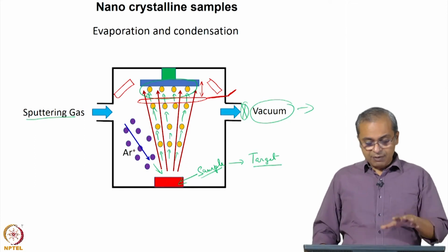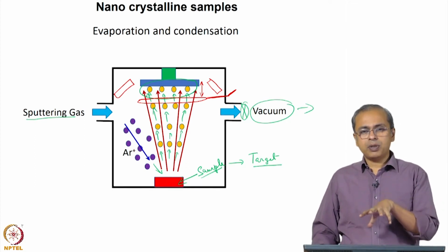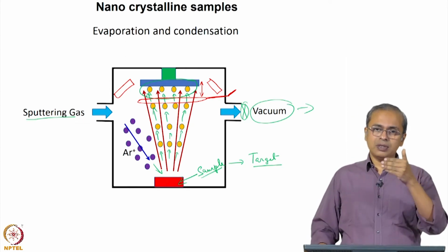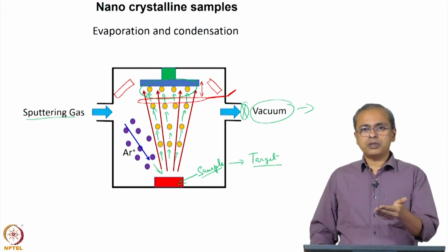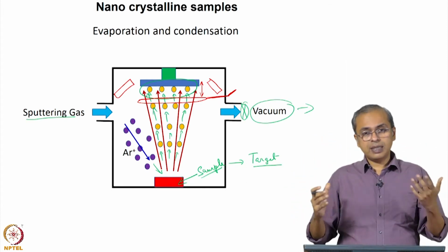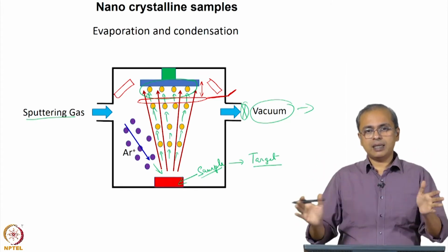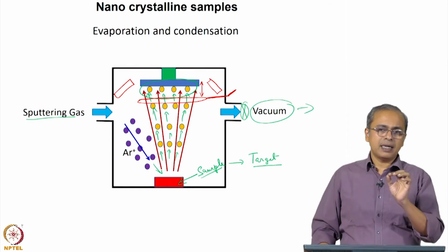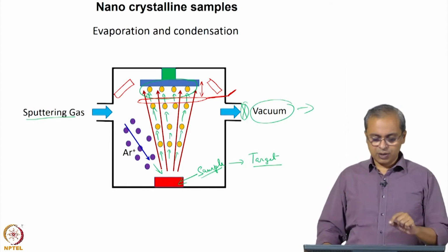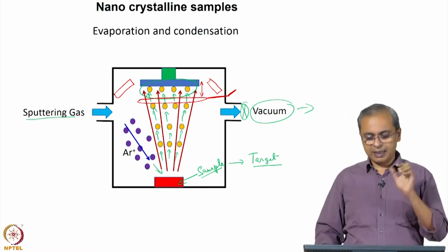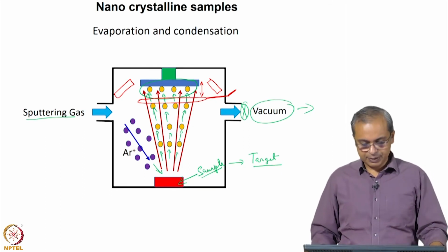And in fact with these units, because the process is a bit slow, it is a good idea for you to think ahead of time what kind of samples you want and put multiple substrates in position, so that you can get all of the samples together in one sputtering process. So those kinds of logistical details you have to pay attention to for you to fully maximize the utility of a sputtering process and get yourself these samples.